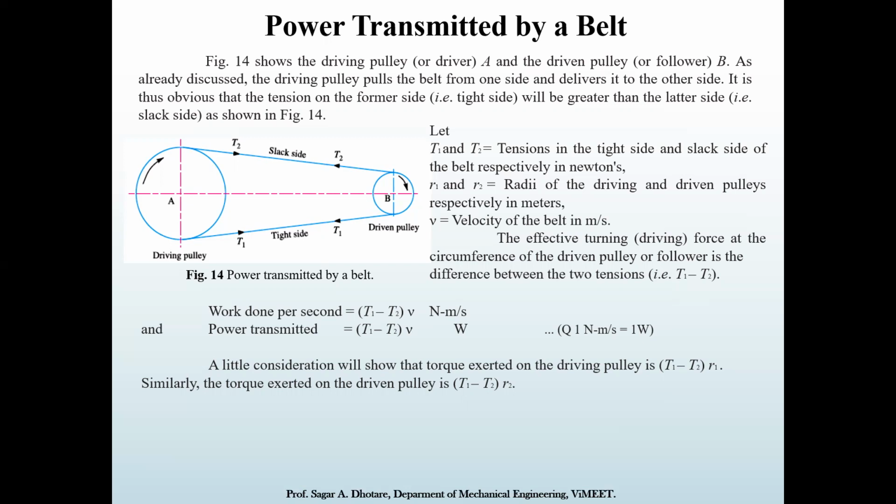Okay, so a little consideration will show that the torque exerted on the driver shaft is (T1 minus T2) into R1, and the torque exerted on the driven pulley is (T1 minus T2) into R2. So while designing the pulley, you should consider this torque or the forces acting on the pulley, and based on that you can calculate the